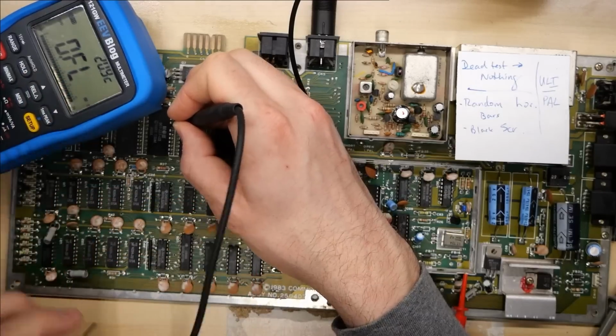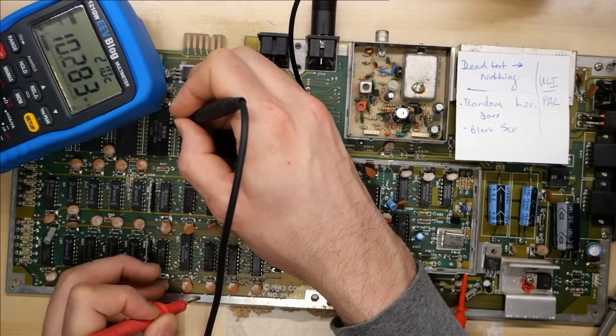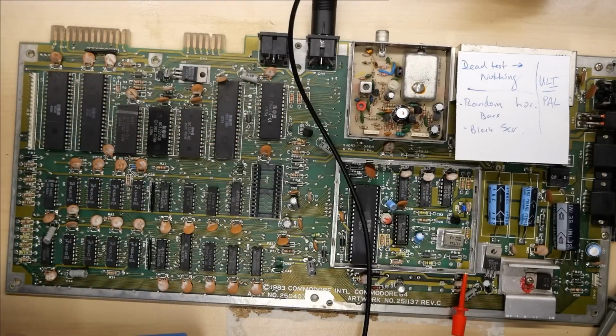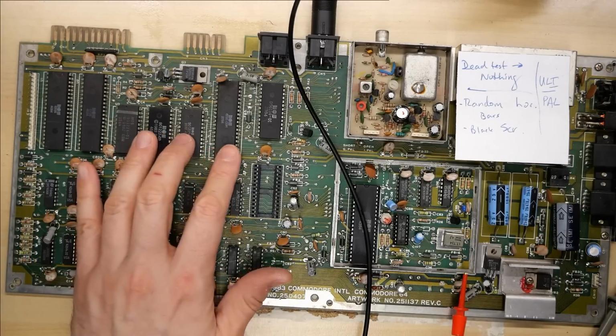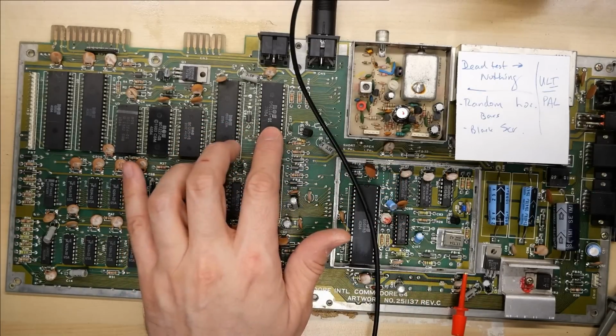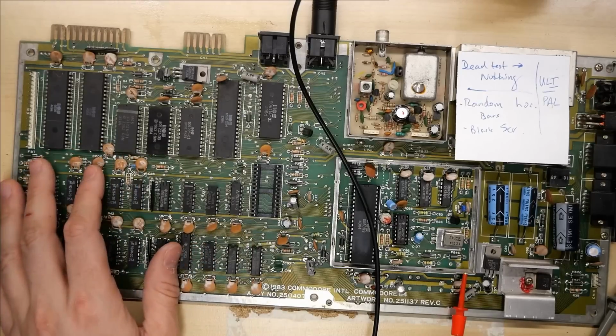Now with the multimeter on resistance, if I check pin 20, it's definitely not shorted to ground. We have, what is this, 10 megohm there. So what's happening when you turn the computer on? I guess it's not a short, it's something holding the pin down around ground. So maybe now that makes me think that it is the PLA that's the problem. And I mean, it's a PLA in one of these bread bin boards.